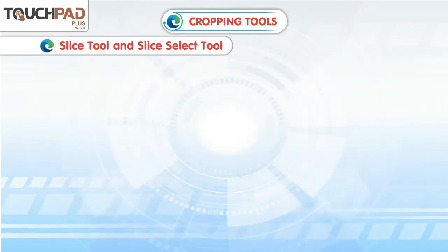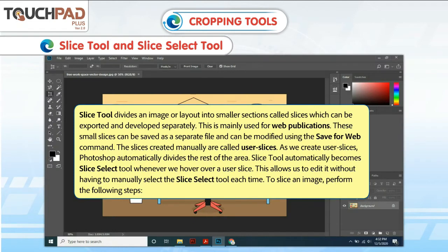Slice tool and Slice Select tool. Slice tool divides an image or layout into smaller sections called slices, which can be exported and developed separately. This is mainly used for web publications. These small slices can be saved as a separate file and can be modified using the Save for Web command.